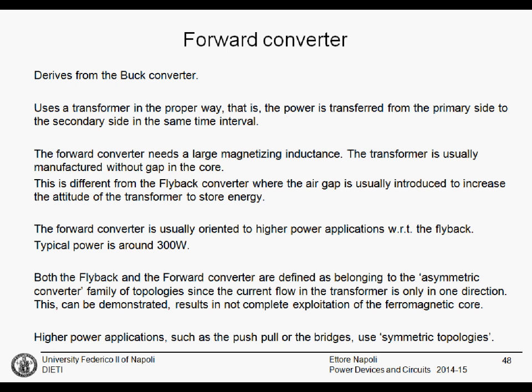Switch mode power supplies are studied and are possible in different topologies. The first one that we studied is the flyback topology, which is usually intended for the lower range of power outputs. The second very common topology is the forward converter, which is intended for a slightly higher power range.